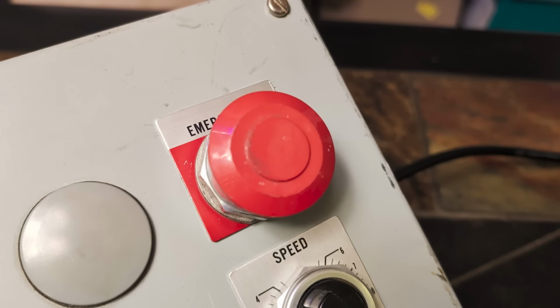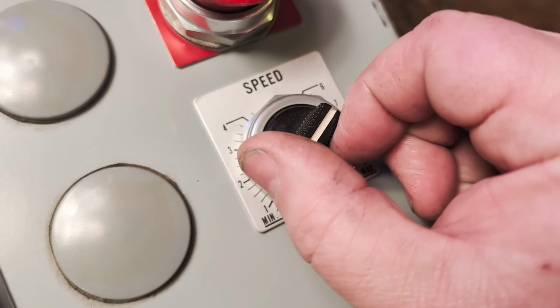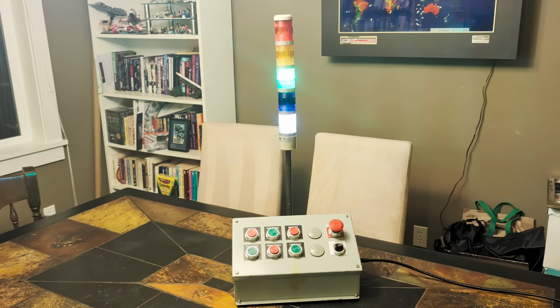Full disclosure, the e-stop is not actually wired up as a real e-stop. All it does is change the state of an input to the Arduino. A real e-stop isn't just another button monitored by software that may or may not be listening. It's something that cuts power to everything, forcing an immediate and totally reliable stop to action. But it's not like this is an escalator or some other scary mechanical device with the power to remove limbs, so... The speed control does what you would expect, changing the delay between each loop iteration in the code. I expect I'll be constantly turning it back down after people leave it running at full speed.